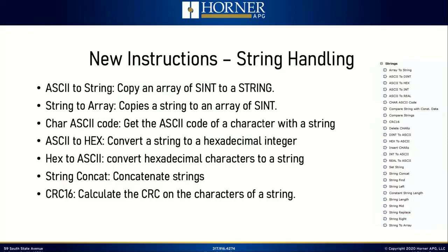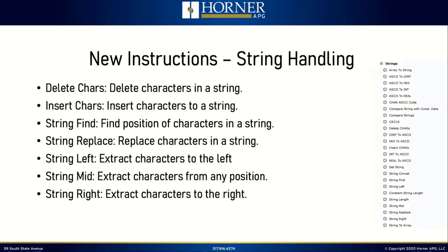I also could do that exact same application using the Enhanced IEC, and I would have a whole host of additional instructions available to me for handling ASCII characters, whether that's converting back and forth between integers and strings, looking up the ASCII code for a character, concatenating strings, or extracting characters from a string from the left side, the right side, somewhere in the middle, whatever the case may be. So Enhanced IEC has added a tremendous number of string-based instructions that you'll be able to use for any application where you need to manipulate strings.